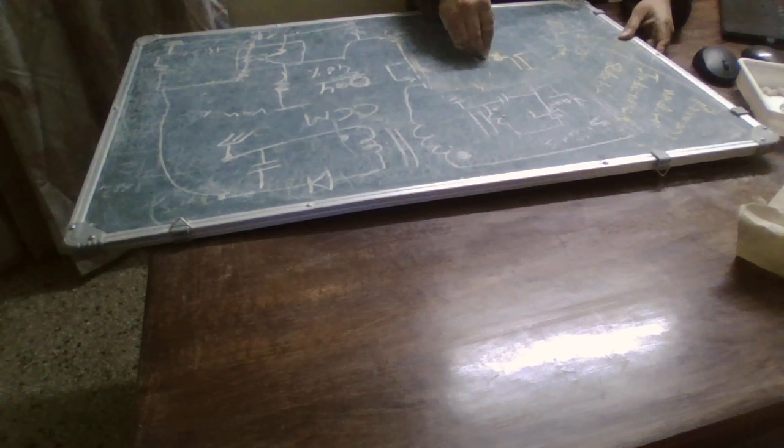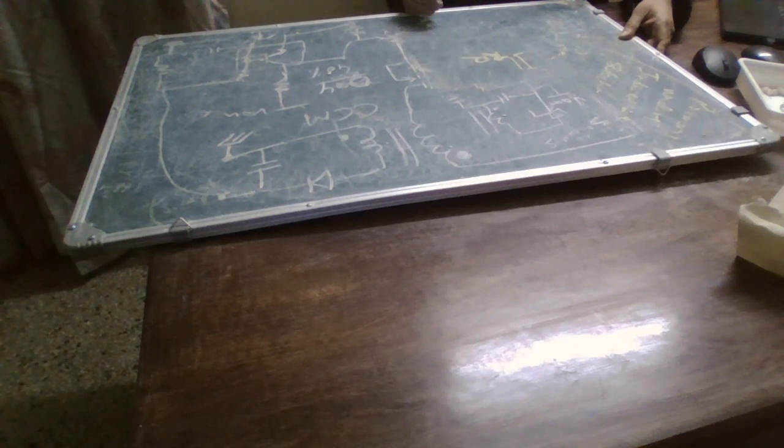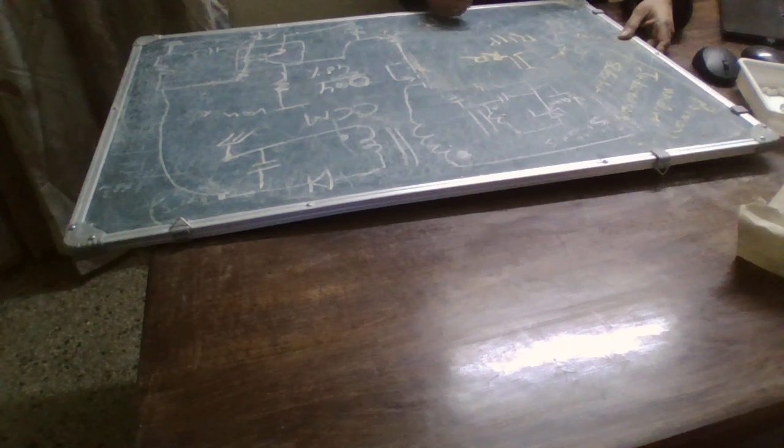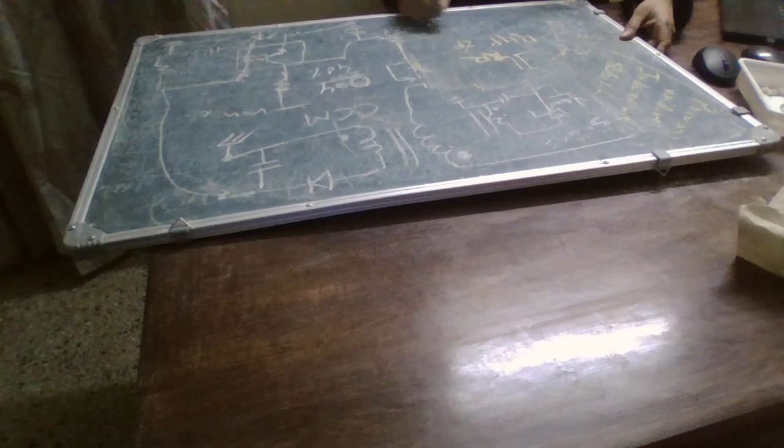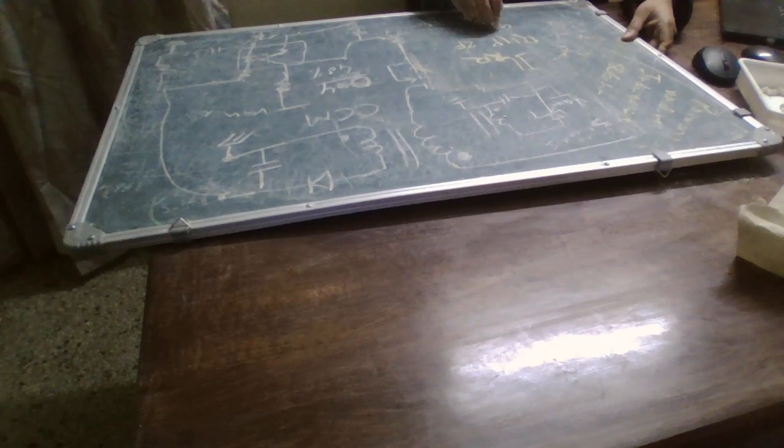The next thing, it's going to depend on the falling slope of the transformer current, and the third is going to depend on the right half plane zero frequency. That means it's an omega Z by ZR.